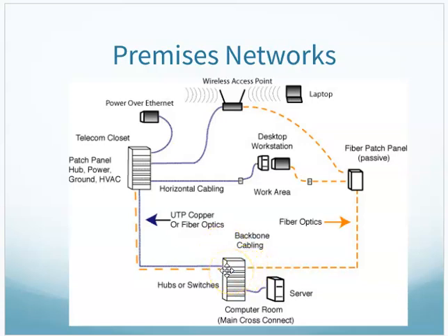let me say this again, fiber going from one closet to the next to connect the closets, and then from there, copper out to outlet boxes to connect workstations, copper out to access points, and then the access points are giving us wireless for the wireless devices. So even in a basic premise system, there's usually a combination of all three for the need.